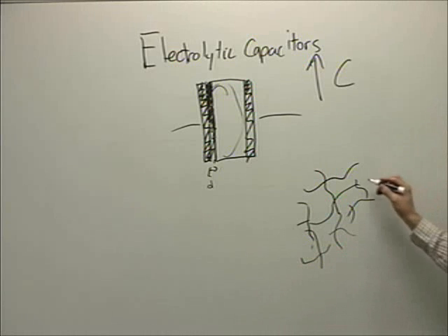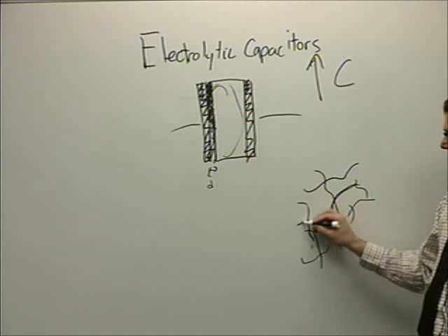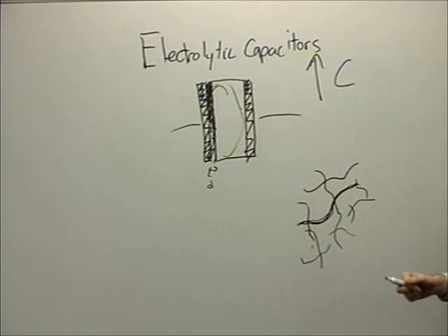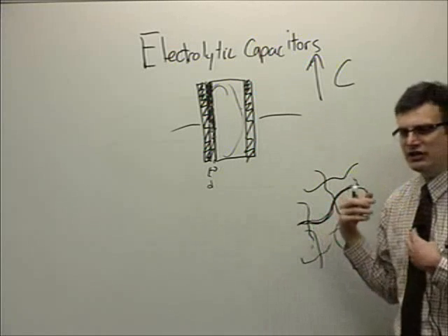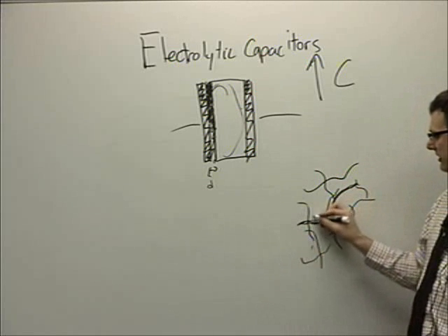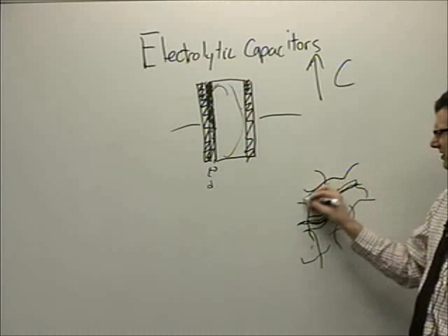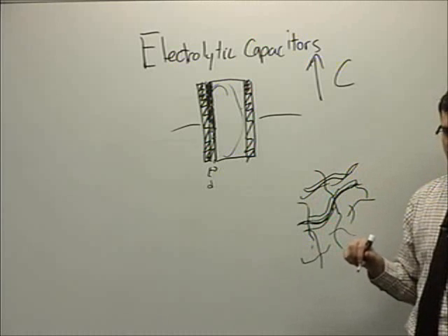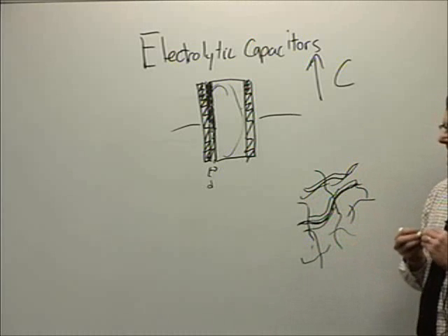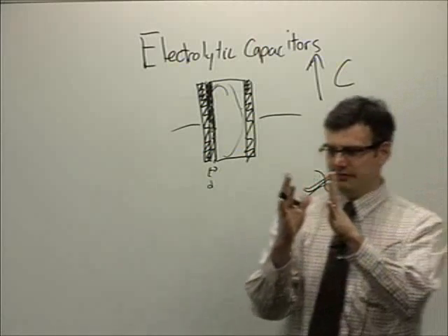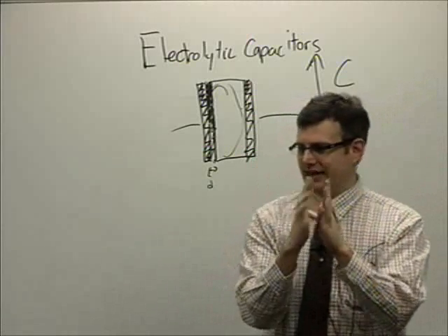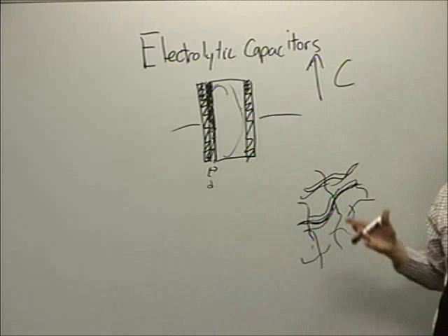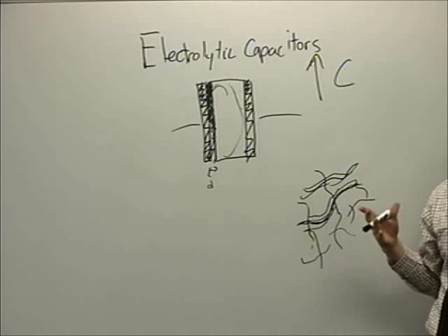The idea is that you metallize these. You dip this in a metallizing solution, put a coat of metal on here, dip it in something like an electrolytic solution, and again you put a layer of insulation around the fibers. Now you've got an electrolytic capacitor, except instead of the area being two plates, it's now the entire surface area of the uncountable number of fibers in the aerogel.